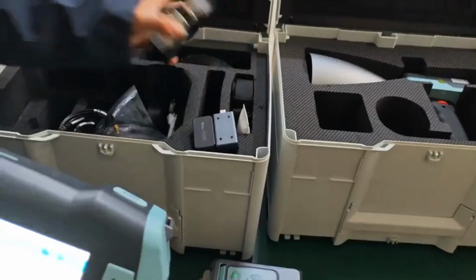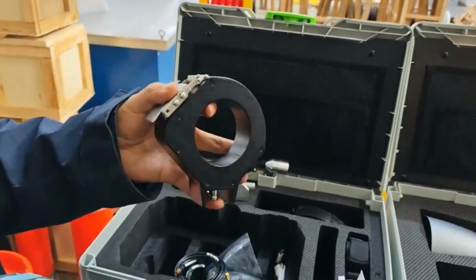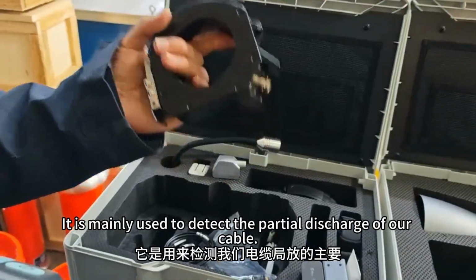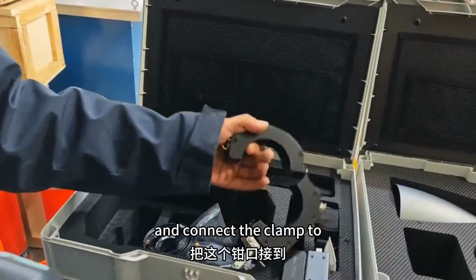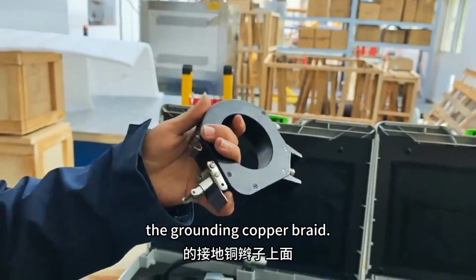And this is a high-frequency current transformer. Just like a current transformer, it is mainly used to detect the partial discharge of our cable. This clamp can be opened and connect the clamp to the grounding copper braid of the cable. The grounding copper braid.